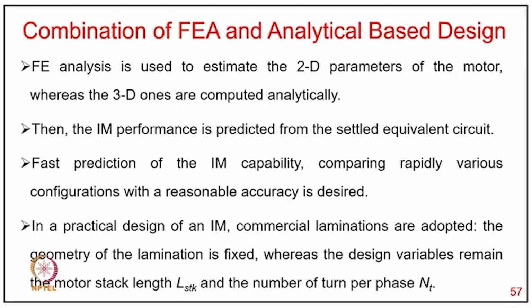Coming now to a combination of finite element and analytical based design. Finite element is used to estimate the 2D parameters of the motor, where the 3D ones are computed analytically. Then the induction motor performance is predicted from the settled equivalent circuit, and fast prediction of induction motor capability, comparing rapidly various configurations with reasonable accuracy, is desired. In a practical design of an induction motor, commercial laminations are adopted and the geometry of the lamination is fixed, where the design variables remain the motor stack length and the number of turns per phase.